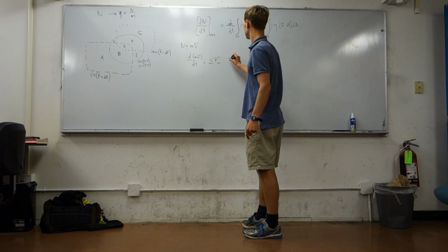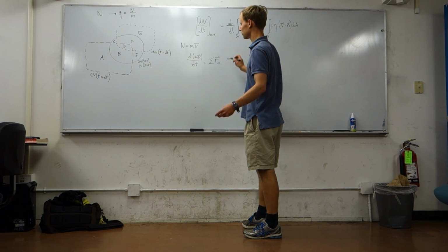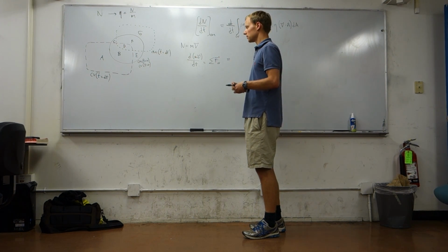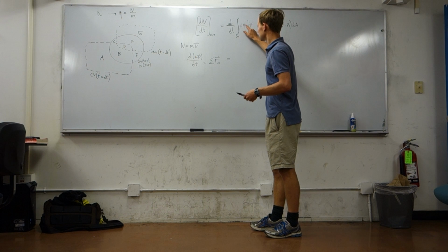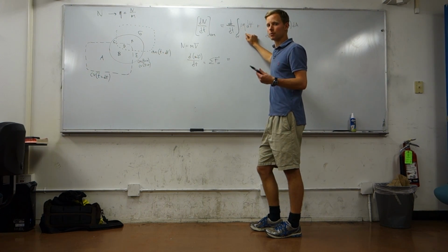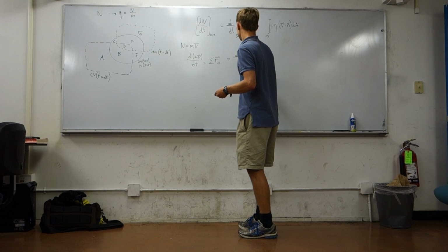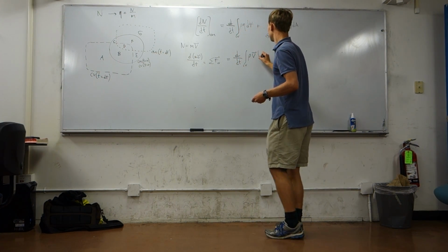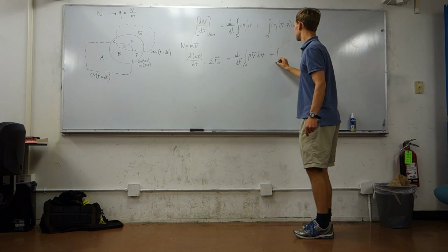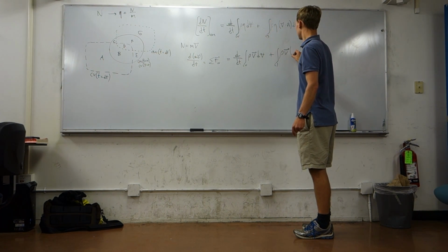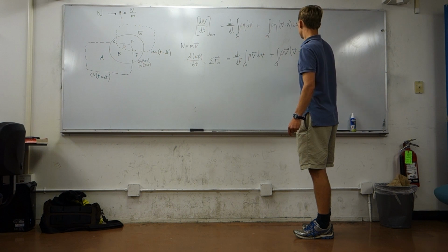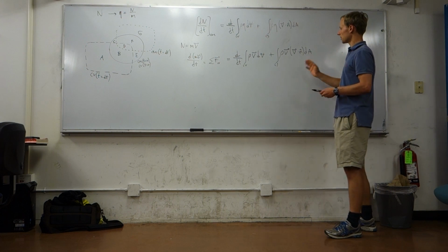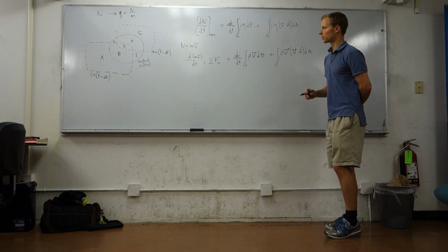So this is the left side. Now we're going to be balancing velocity, linear velocity. And we need to be careful about which reference frame we're balancing our velocity in. Whenever we deal with this, we need to know what eta is. And for velocity, that means we need to know the reference frame in which we're measuring the velocity. So just keep that in mind. Plus the flux terms. And these velocities are currently notated to be the same, and they could be the same, but it's not always the case that they're the same. So this is where it's really important to understand Reynolds Transport Theorem rigorously.